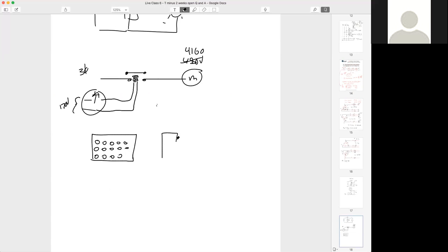You can have a run, jog, stop button. You can have a 3-position hand-off-auto switch. You can have these all in close proximity, and your motors can all be hundreds of feet away in all sorts of different directions. So it prevents us from having to physically be responsible for switching the higher voltage that the load needs to operate.